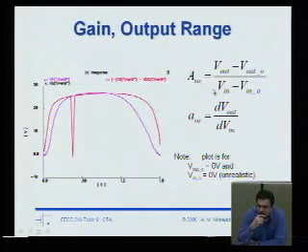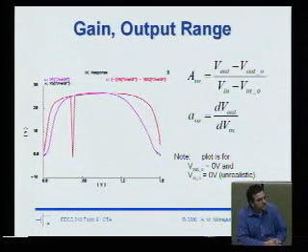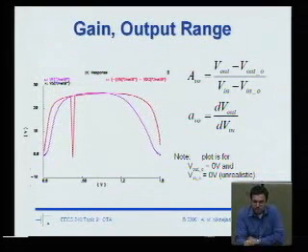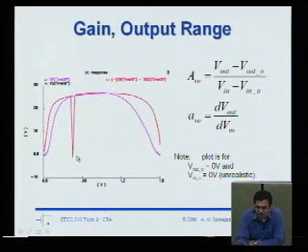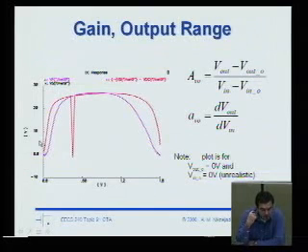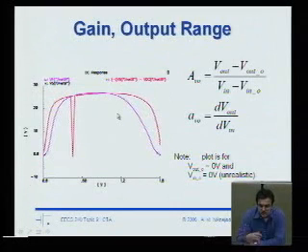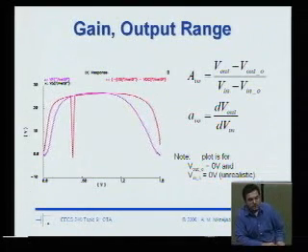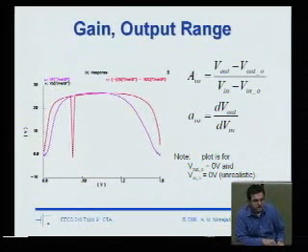The large signal gain is how much the output deviates from its DC point versus how much the input deviates from its DC point. If I plot that, neglecting this little point here, I get this red curve, which shows that for large signal conditions, I actually have a wider range where the gain is bigger than 20, if that's the spec I'm trying to get. Okay. First of all, which is really important, small signal gain or large signal gain? And two, why is the large signal gain better?